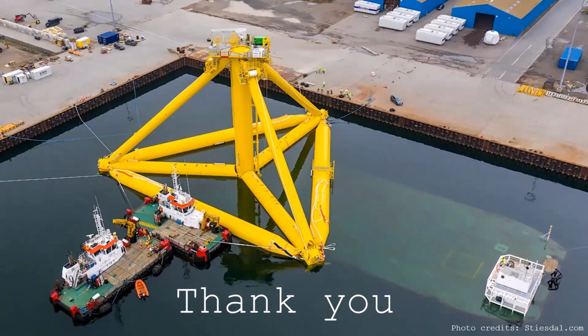F other can be gravity. It can be your mooring lines. Actually, added mass: when you look at the Kirchhoff-Kelvin equations for theoretical hydrodynamics, these are equations that show you the forces you have due to added mass. And there are some things that are proportional to accelerations. That's the ones that we have in MA times A. But there are also some terms that are just proportional to the velocity, and they would go into F other. So you should just think of F other as anything that's not proportional to the acceleration. Lump it all in there.